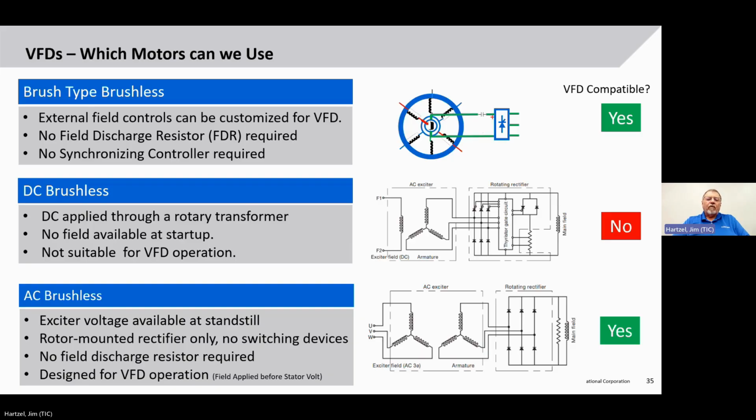Remember, that was one of our requirements for the VFD, that we can apply the field before starting the drive. There's no synchronizing controller required, no field discharge resistor. So can we use it on a VFD? The answer is yes.